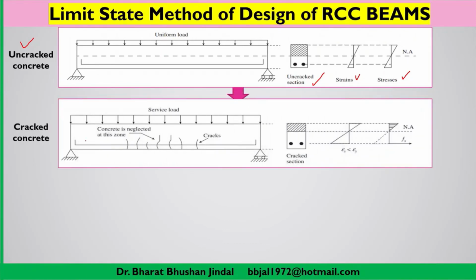Now the next stage is cracked concrete, which we have discussed. When you are increasing the load, even in this diagram you can compare. Here the load is lesser, here the load has increased. Now when the load has increased, what will happen? Some cracks will start developing at the bottom of the section. Reinforcement is there. Now when this portion of the concrete is cracked, we will say that concrete is neglected in this zone for the calculation.